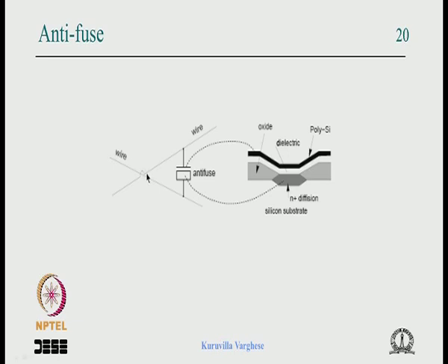So essentially if this is assumed to be a horizontal wire and this is a vertical wire, normally at the cross point there will be a hole drilled, and that will be conducting, it is made conducting. Okay, so in anti-fuse FPGAs the connection is made through this hole. Initially the hole won't be conducting, there will be a special fuse material deposited, it shows a cross section of that, and normally it is not conducting.